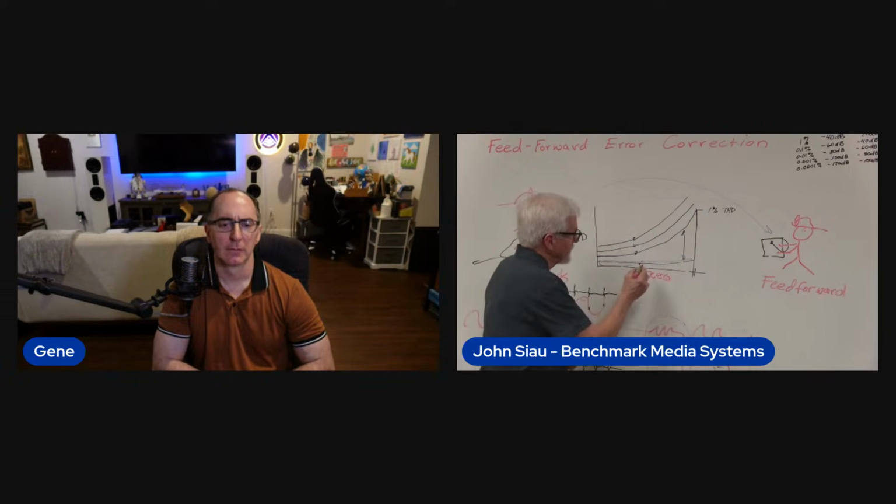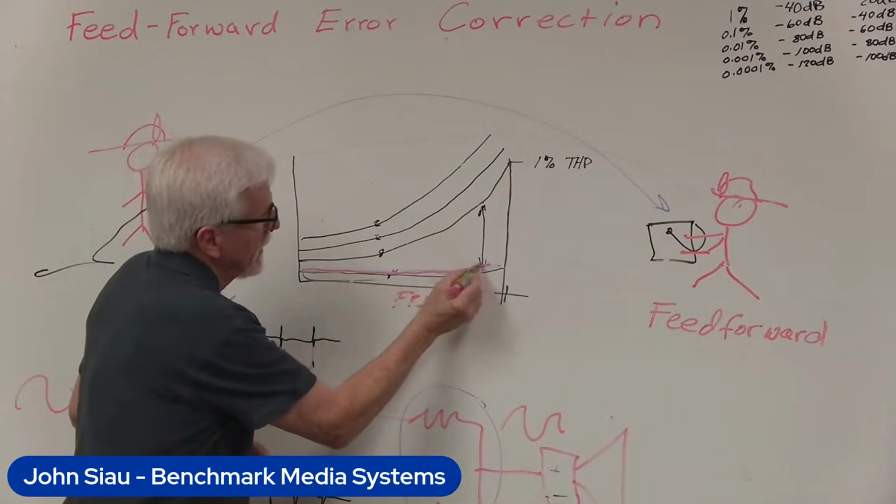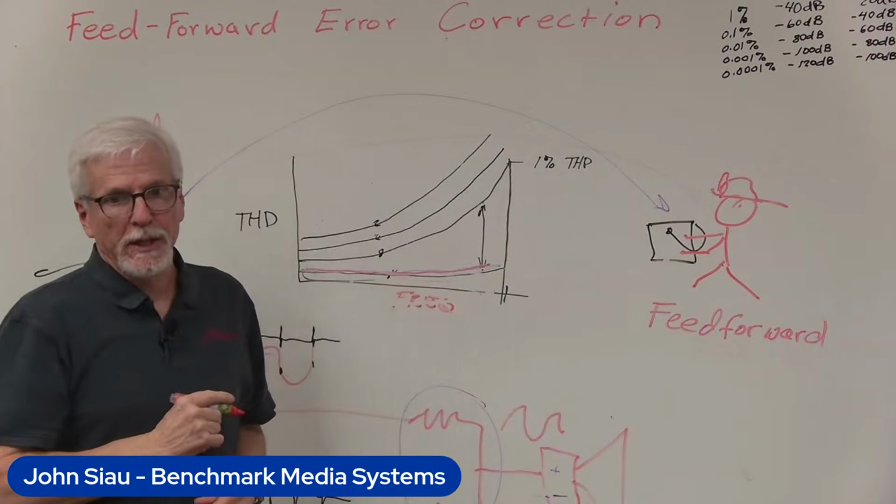And it's interesting because a lot of amplifiers, when you bridge them, you only get maybe twice the amount of power because they're really current limited. Right. You're getting close to theoretical. Theoretical bridging should give you 4 times the power. Right. So we're very close to that 4 times the power, and what's also very important is that this 4 ohm line is right on top of the 8 ohm line.